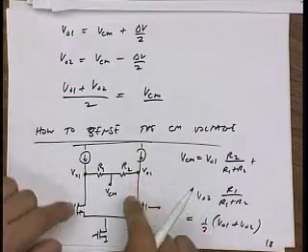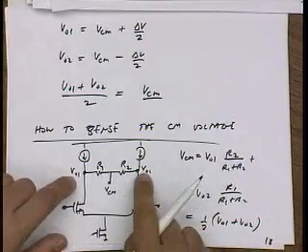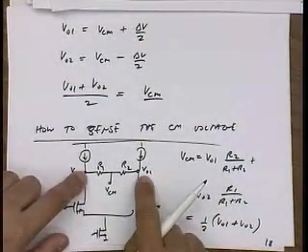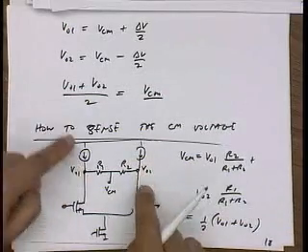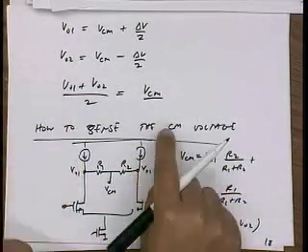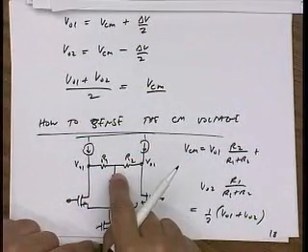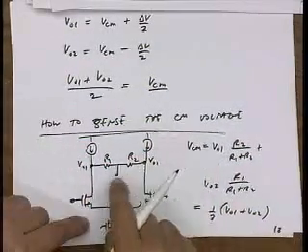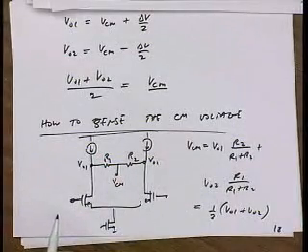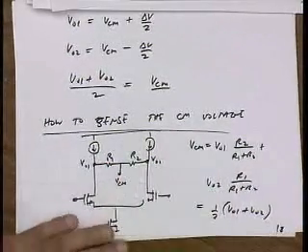That's nice because this voltage only depends on the average common mode voltage. If I have a differential voltage, this goes symmetrically up or symmetrically down, this point will not move. So this is not sensitive to a differential output, it's only sensitive to a common mode output. Okay? What's the problem with doing this?